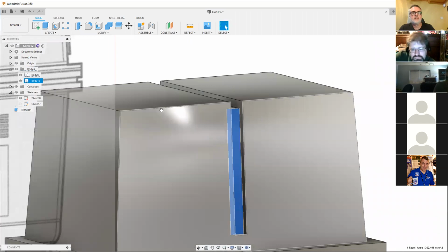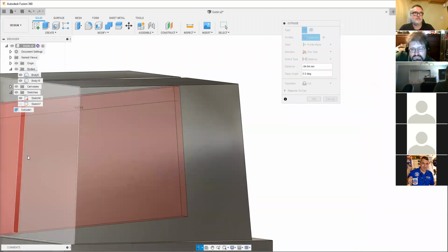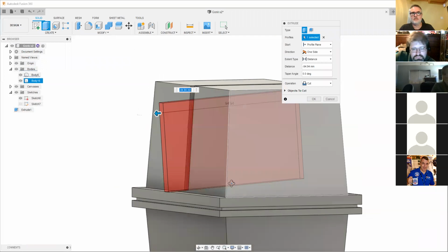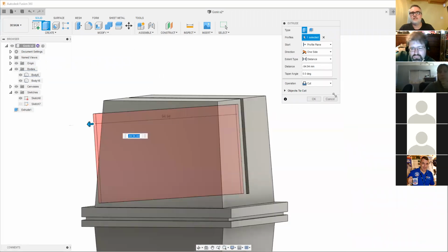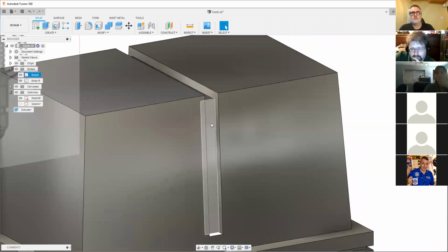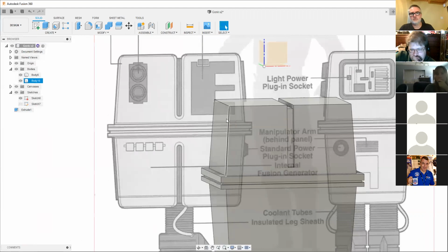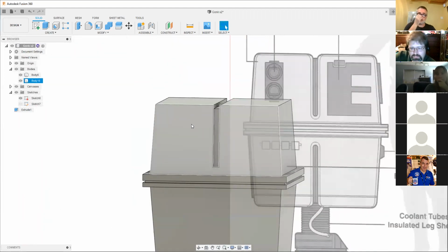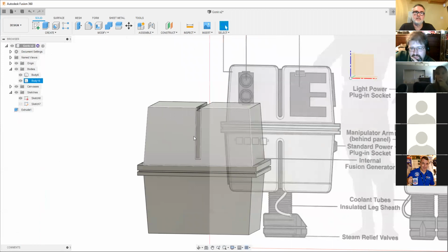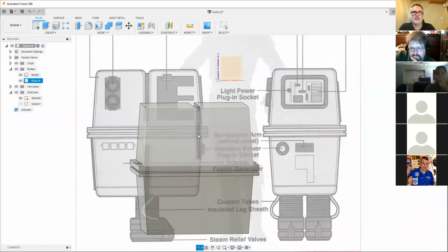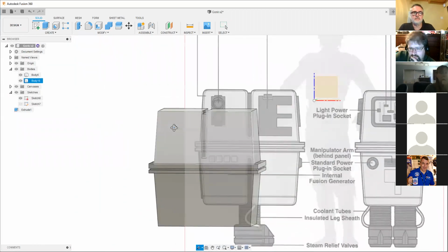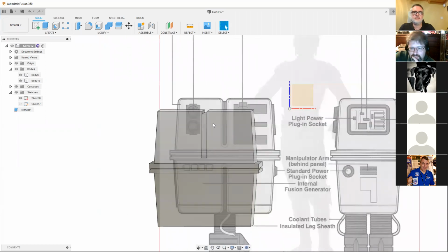When I pushed it in, the extrusion would go down. So if I pulled it right through to the other side, it'd be an offset, if that makes sense. Whereas with press pull, it'll keep it level. So relative to the origin, right? Relative to the origin, yeah. So it's worth playing with the two, just so you can get to see when it's appropriate to use either. Makes sense.